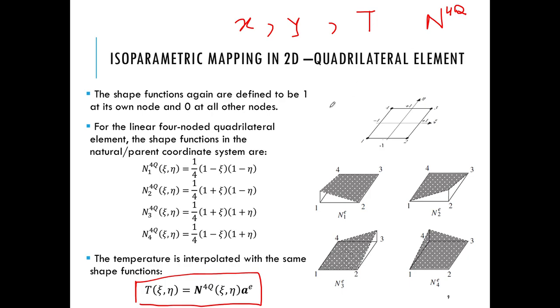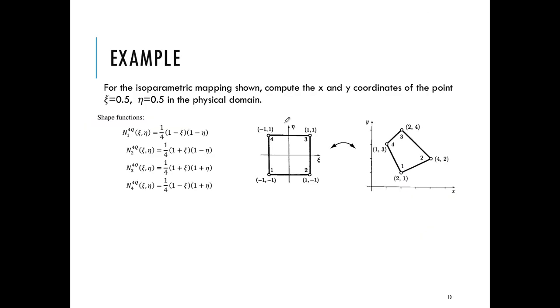So this is how far we had got, and at the end of last week I left you an example to do. Essentially, we wanted to use our quadrilateral isoparametric mapping, that is, we use this 4-noded linear parent element to map onto our arbitrarily shaped linear quadrilateral element.